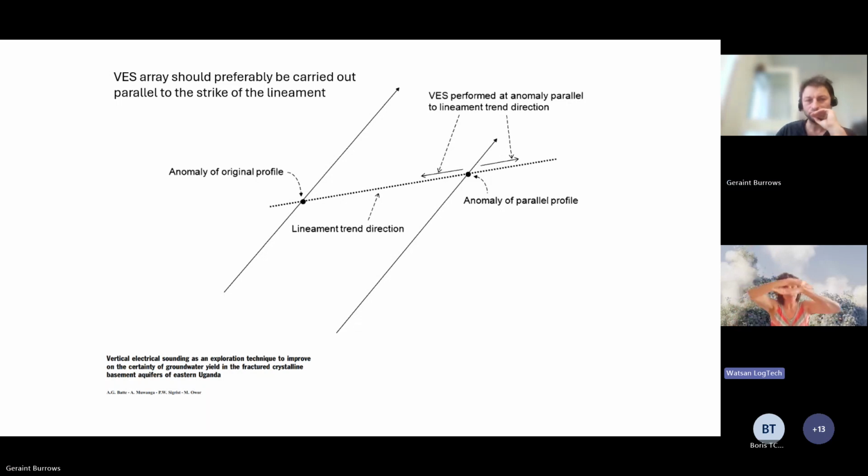Then you assume there might be something like a crack below that crosses perpendicular, mostly. Yeah, you're hoping to pick up this lineament, but you might have planned it out to try and pick it up. You then pick it out, and sorry, I interrupted. No. And then is when you start expanding your electrodes in order to go more in depth and lateral about what this lineament looks like.